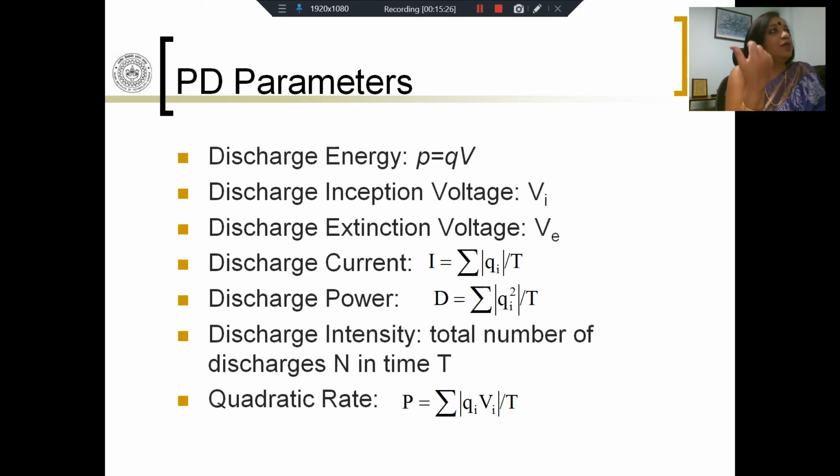Now, when you increase the voltage further, it is not necessarily that you will see an increase in magnitude. Remember our discussion about the pulsative nature of PD and how we showed that the ratio of the breakdown voltage of the void to the voltage that is applied across the void determines the number of pulses per cycle.